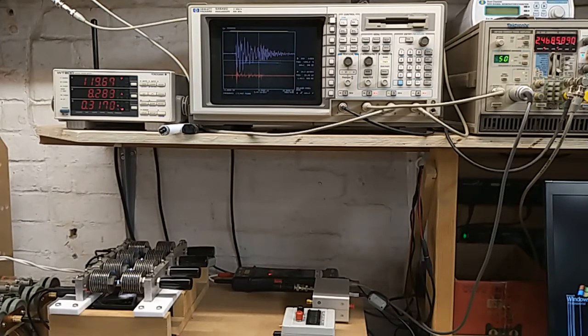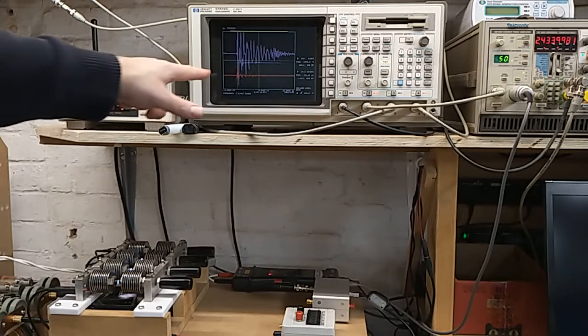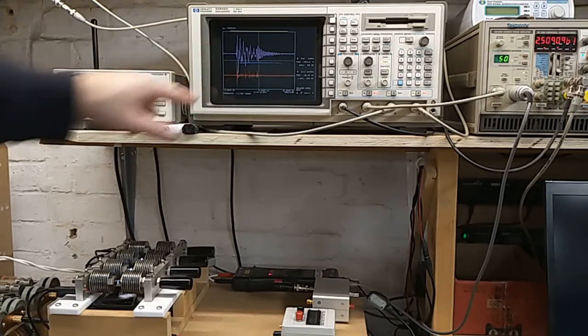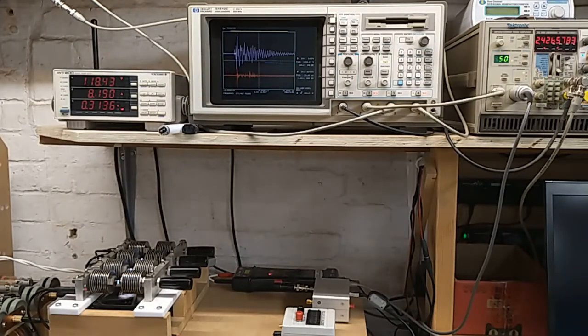Okay, we just take another look at the oscilloscope. We can see the red trace, which is the current in the single wire. We're running just around about 300 watts, but the burst current at the beginning is quite high. Now that's calibrated at 50 amps per division, and that implies that some of those currents in the single wire are quite large.